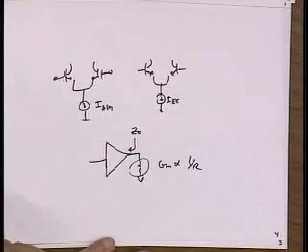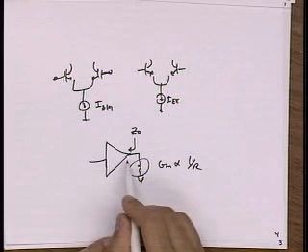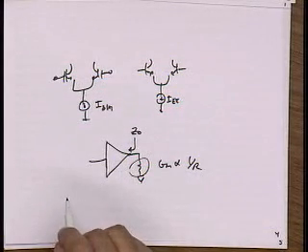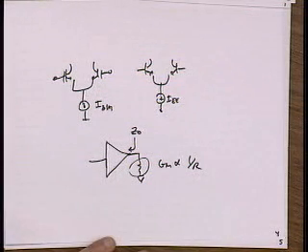And if you do a more full analysis, you see that you start losing bandwidth too. So let's say I conservatively say this resistor should be 10 times bigger than 1 over GM. That pretty much sets the gain bandwidth product of your amplifier.